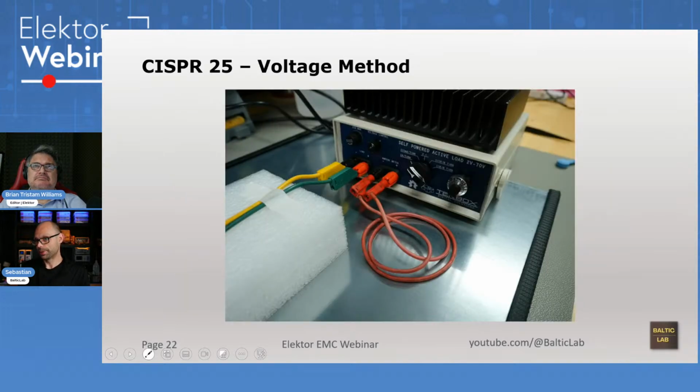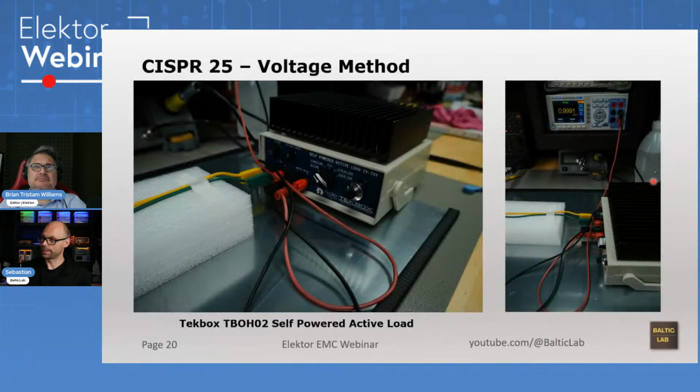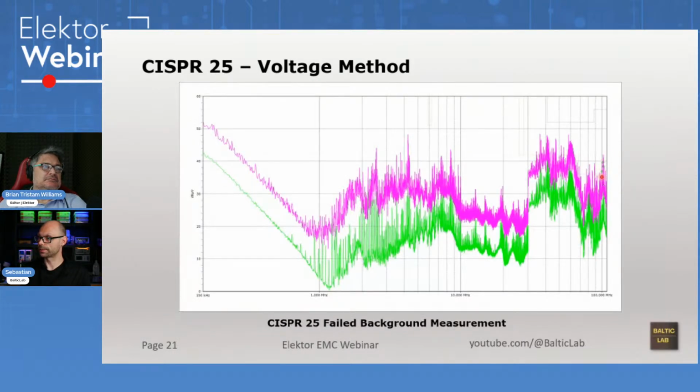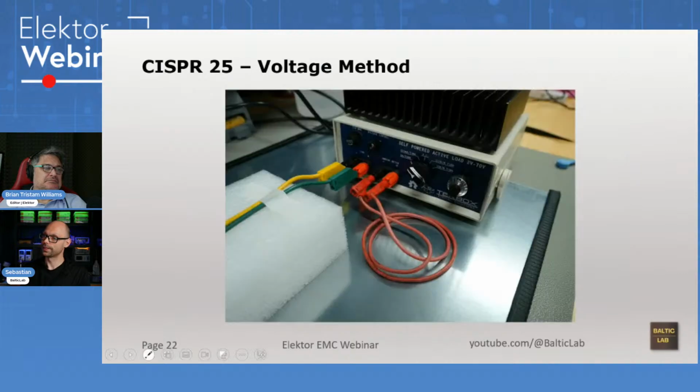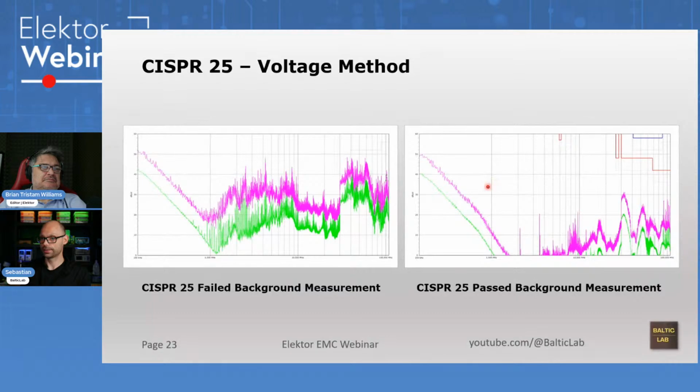Well, remember those long leads that I had previously for current measurement? Actually, let me go back. That long stuff over here. Of course, this is a perfect antenna for all kinds of interference. And if we look at the frequency range, we can see that this is the FM broadcast band. So even that's not perfect, but just for fun and for comparison, I simply connected the two ports directly to each other, and look at the difference. This was measured beforehand, and this was measured afterwards.